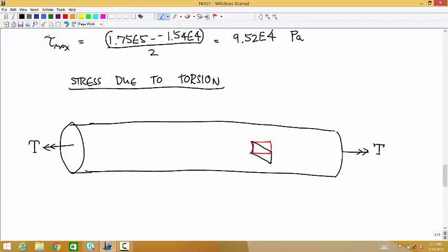All it does is angle change. It doesn't change length or anything, it just changes angle. And so now think about what kind of shear force you would need to make a stress element do this. On this side it's down, and then that means on this side it has to be up. This side it has to be that way and that way. When twisted like that, right? It's not like coming out of the page.